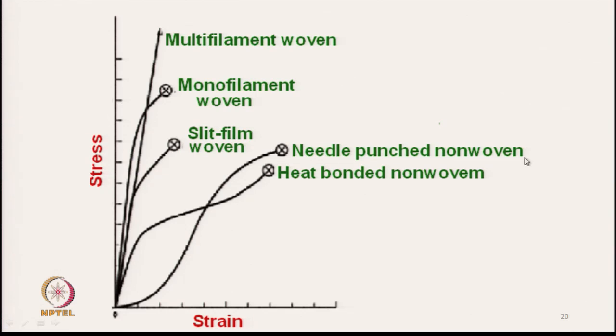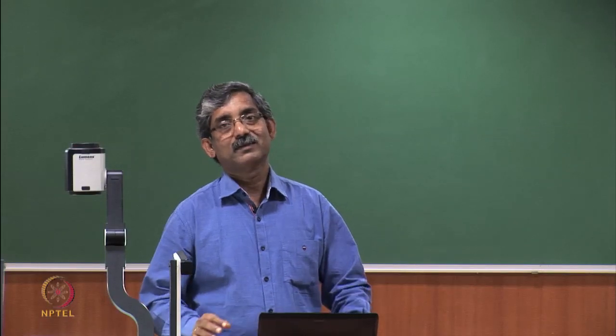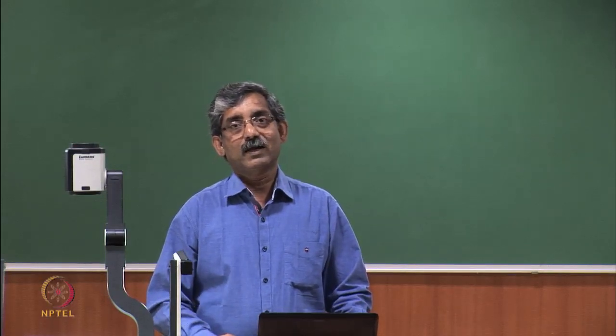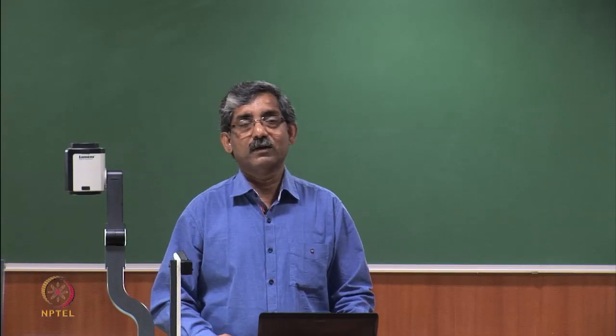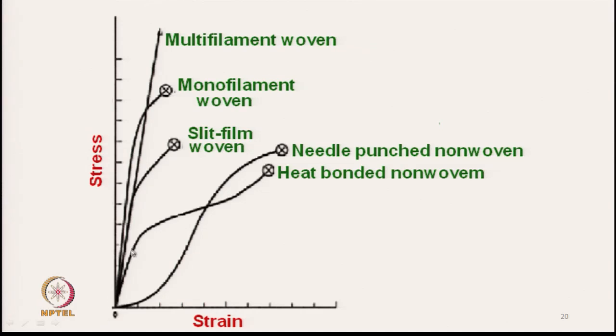And as far as non-woven geotextiles are concerned, the needle punched non-woven geotextile has got least modulus, and after certain strain the fabric starts showing gain of stress due to reorientation of the fibers, whereas heat bonded non-woven fabrics have relatively higher modulus.